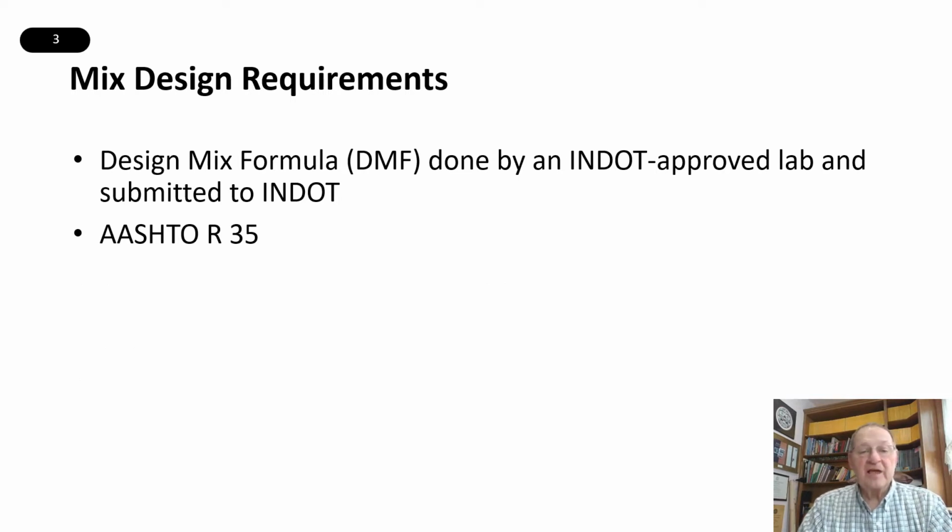So the first thing about doing a mix design is that we will end up submitting it to INDOT for approval. And in order for us to be able to do that, we have to be an INDOT approved laboratory. If we have not gone through the approval process, that is a requirement to submit a mix design for INDOT. So we need to get that done. Now, in terms of what AASHTO specifications are used, it is basically AASHTO specification R35 that is being used to do the mix design.